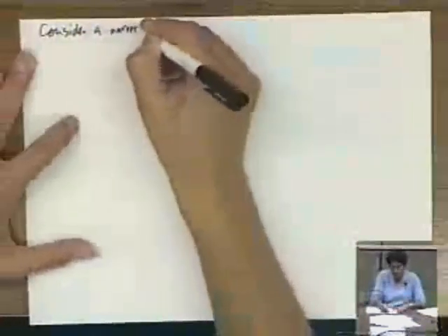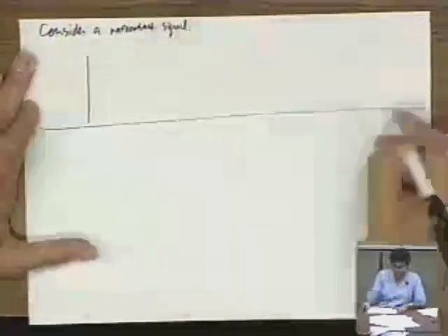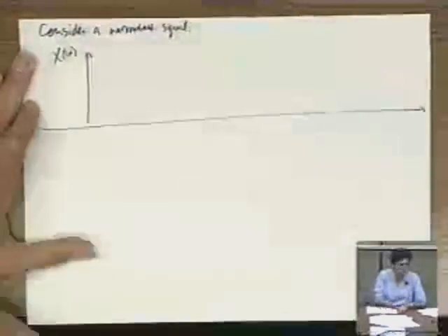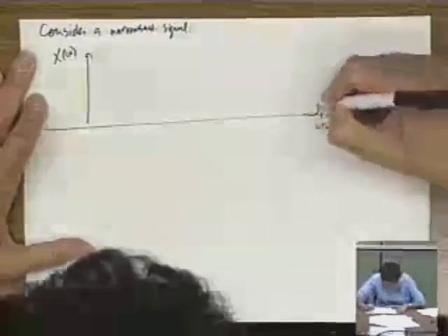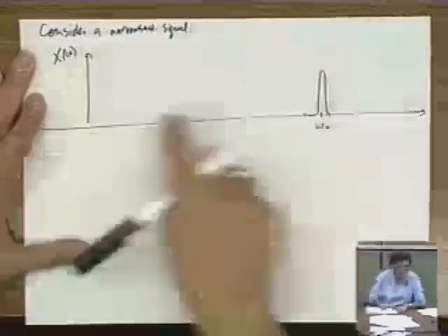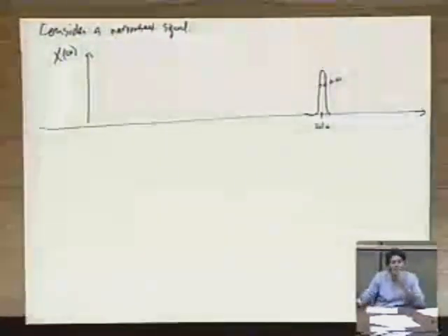Okay? So how can I now be a little bit more formal about these linear phase systems? And what can I show about them, or what can I say about them? Well, consider a really narrowband signal. And what's the meaning of a narrowband signal? Well, a narrowband signal is one whose discrete time Fourier transform X of omega is centered around omega naught, but its bandwidth, delta omega, is much, much smaller compared to omega naught.